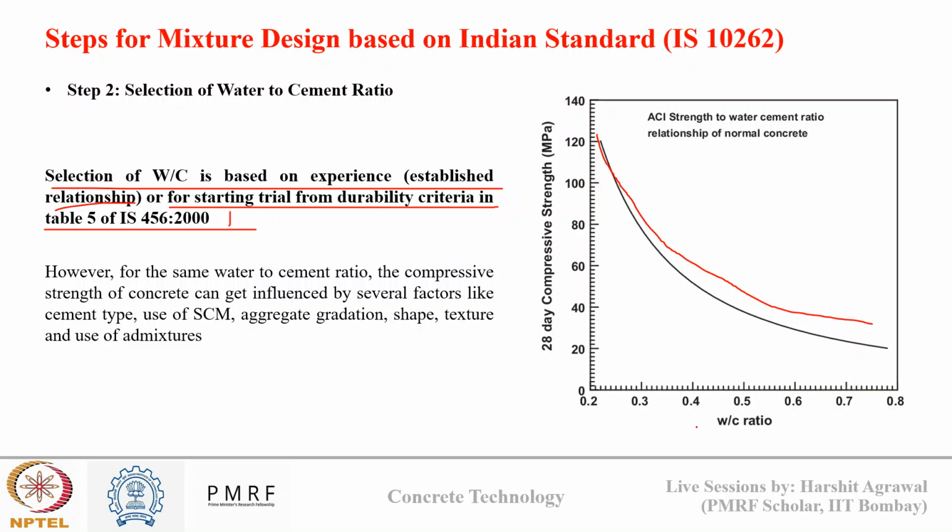Now this chart says that W/C ratio is the only factor which is influencing the compressive strength. However, just relying on W/C ratio to get a strength may not be enough. Okay, and that's why a trial mixture design is done first.